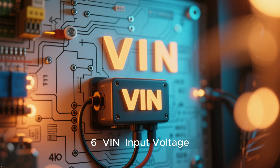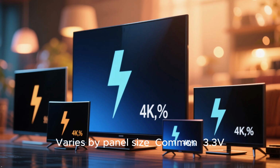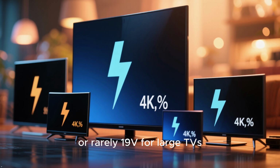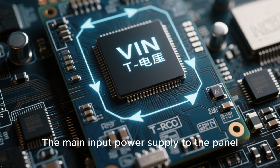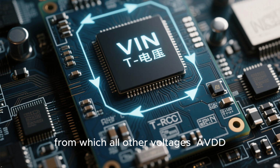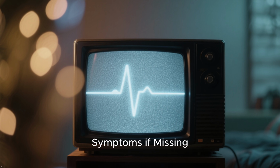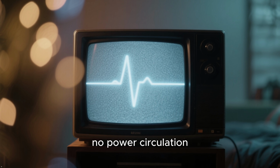6. VIN, input voltage. Typical value varies by panel size. Common, 3.3 volts, 5 volts, 12 volts, or rarely 19 volts for large TVs. Function: the main input power supply to the panel. It feeds the TCON board, from which all other voltages, AVDD, VCOM, gamma, etc., are derived. Symptoms: if missing, no display, the panel remains completely dead, no power circulation.